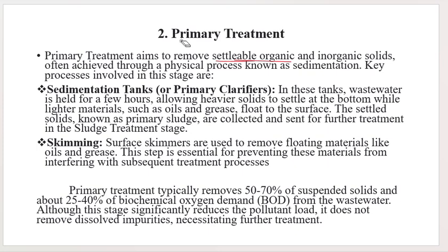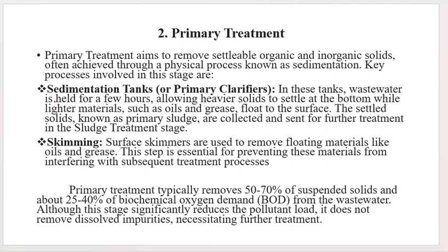Okay, so there are multiple stages in this primary treatment. The first stage is the sedimentation tank. There will be a tank after preliminary treatment. After preliminary treatment, the water will flow to this tank. The water will be kept for a few hours in this tank, so the solid materials will settle down to the bottom, and later this will be removed. This is the sedimentation tank, also called the primary clarifier.